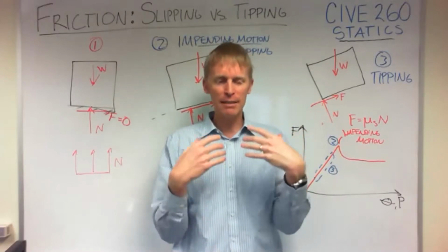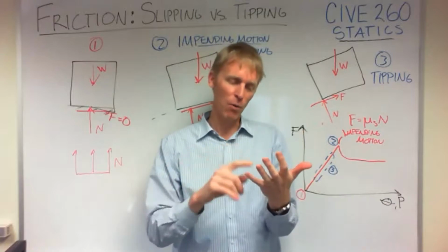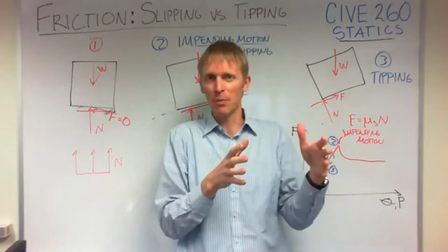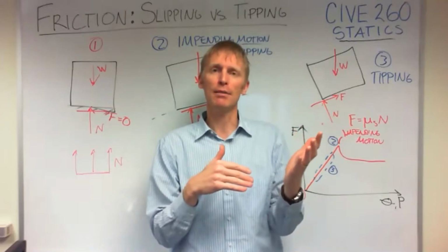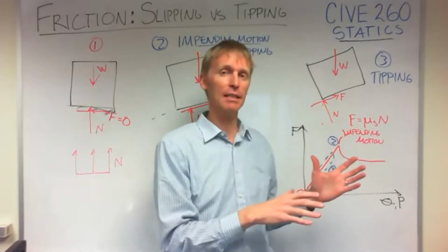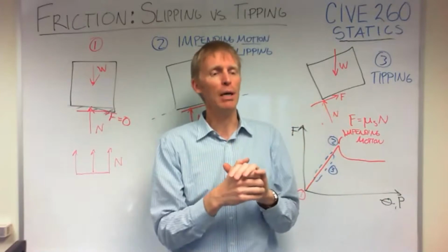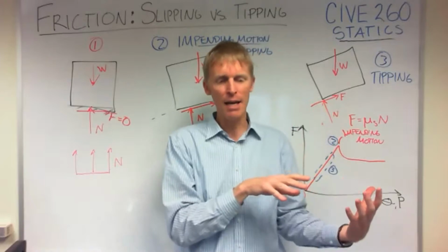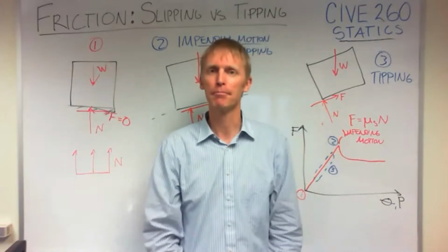And so often as an engineer, we want to design for the worst case scenario, right? So we're like, all right, if there was wind and the road was icy and these different things, what would be the optimal speed, which is also exactly why you see variable speed limits on some sections of road, because they've actually pre-computed what's going on and say, hey, given this surface condition, and so that's related to stopping distance as well, which is another friction related item. But what's the safest speed? Essentially, these assumptions we made in design may not hold true anymore if it's icy and cold and wet and whatever else is happening.